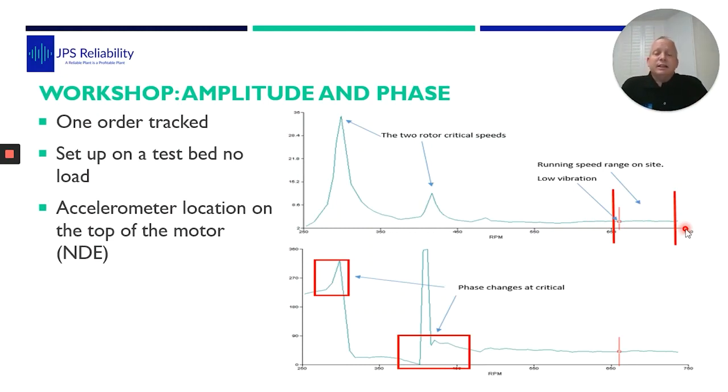So we confidently say to them, there's a resonance issue. It's nothing to do with the motor. The motor is a force, but it's causing the bed plate to move, which is causing your motor to twist like this. So this motor went back on site.